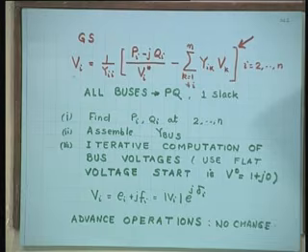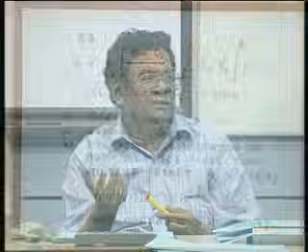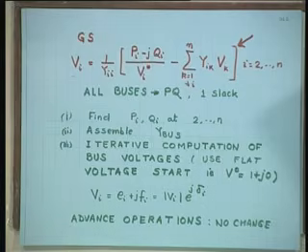buses. If you recall, for the approximate solution, we assumed all were PV buses, it suited us, because we did not want voltage to be an unknown variable. The moment voltage becomes an unknown variable, they do not remain linear equations, they become non-linear equations. Z is equal to xy is a non-linear equation if x and y both are variables. But here we are just opposite, which is close to reality.